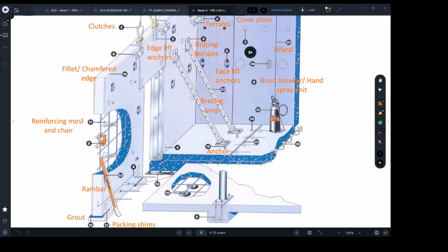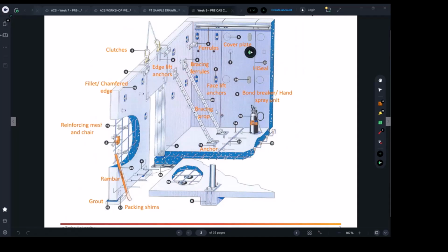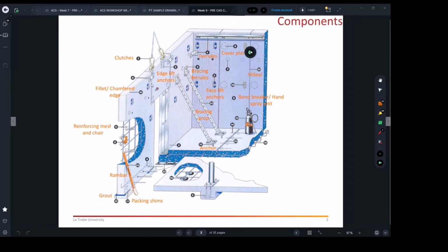Such systems typically don't use in situ. In situ is only used for special features where you have to build them on site. Maybe if you have a few walls in a building, you may think about building it in situ. But if you have a warehouse where most of its surroundings are precast panels, then nobody will build it in situ, right?